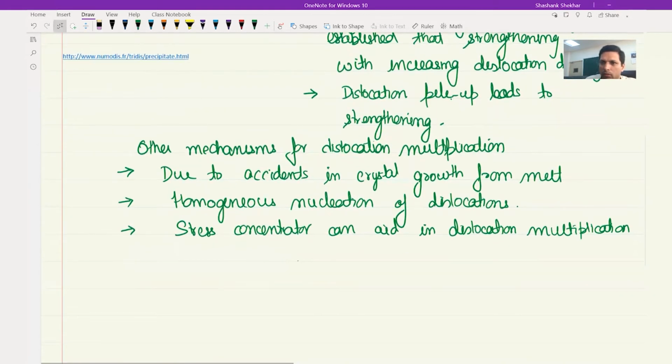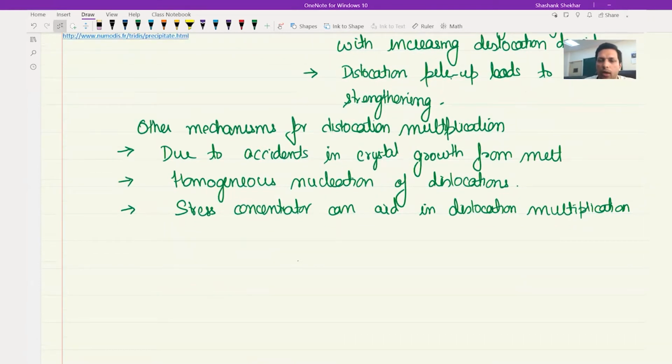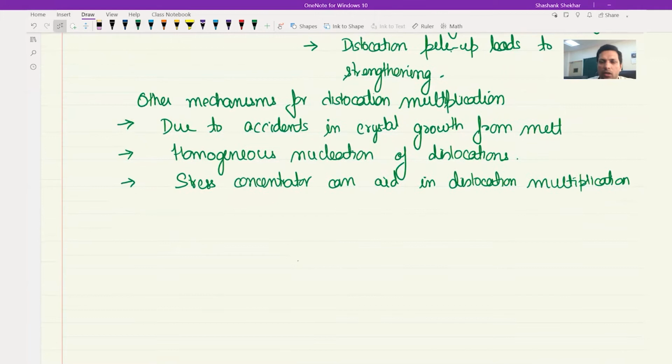And if we look at the dislocation multiplication, from one of the books by Dieter, you would see that by just deforming a material by a few percent, so if you are applying a strain of a few percent, the length of dislocations becomes as high as 50,000 kilometers in each cubic centimeter.